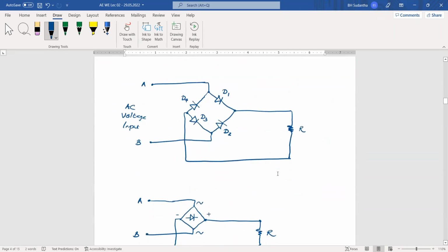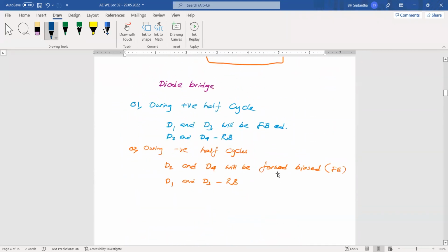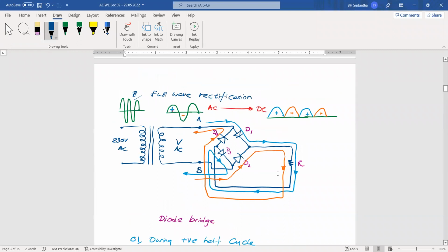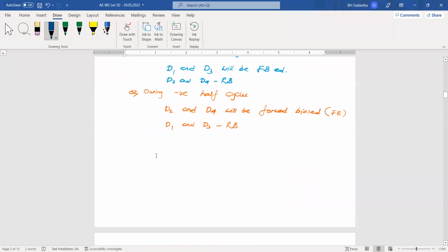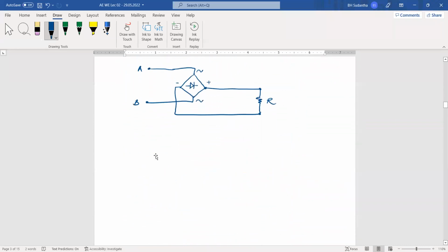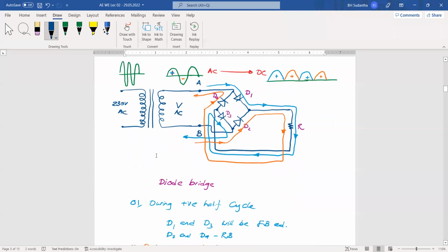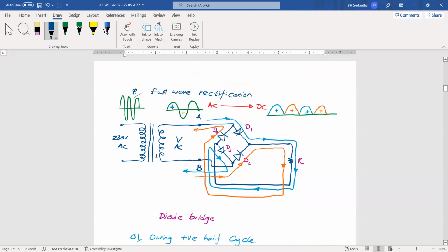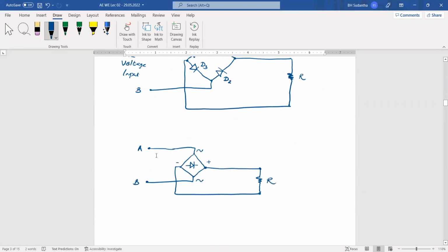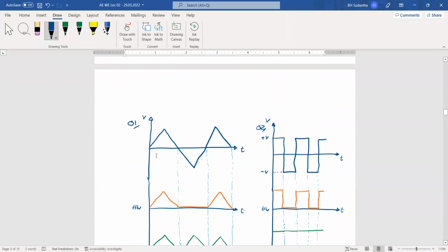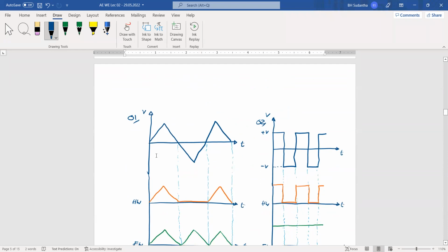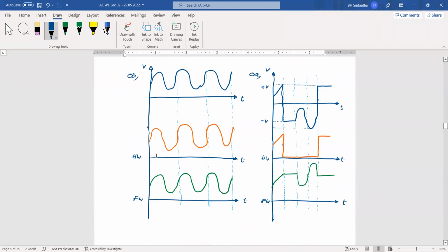But anyway, here, this transformer side is not necessary all the time. I have included this transformer side to help you understand how we can provide this voltage. That's all. Then again, these input side voltages are not smooth. A higher ripple voltage is there. We have to have a smoothing mechanism. The simple smoothing mechanism is adding a capacitor.